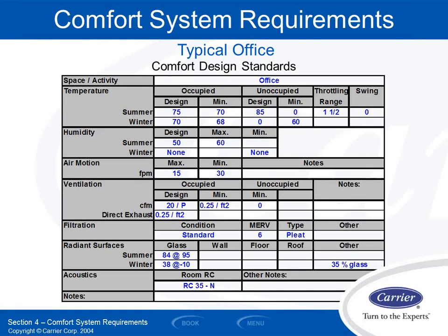I'm a fat guy, I got to be cool in my office. You get those comments all the time. That oftentimes initiates with people expecting it to be much colder because they have oversized equipment in their current lifestyle, and they need that colder temperature to get the humidity down. Right? If you're able to keep the humidity in check by correctly sizing the equipment, you probably don't need those